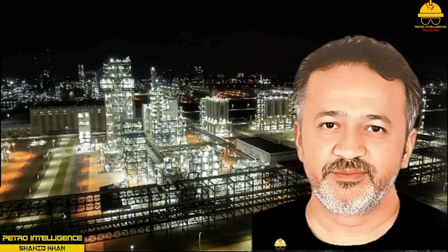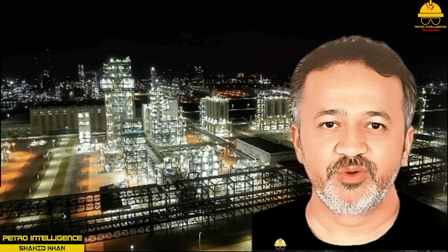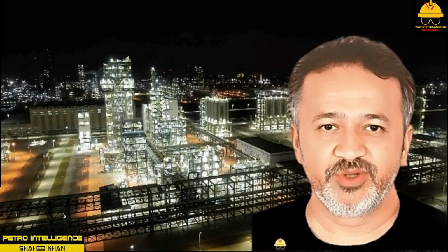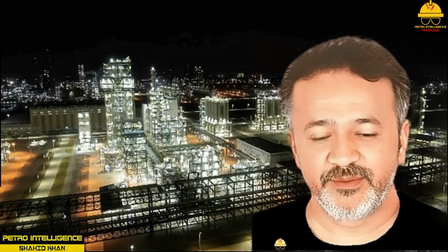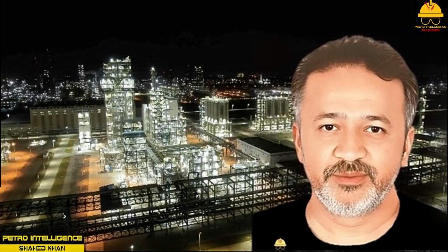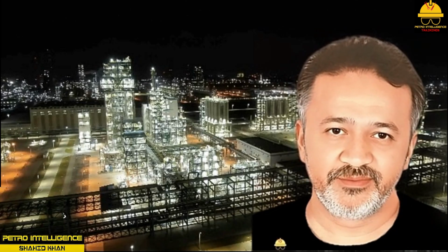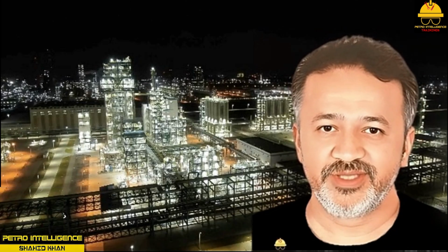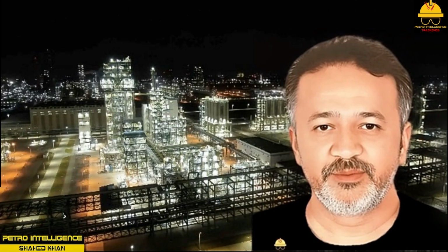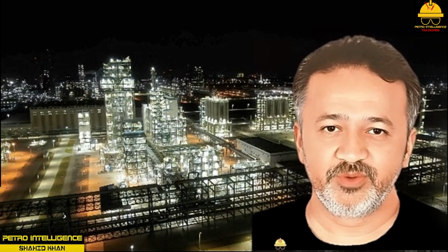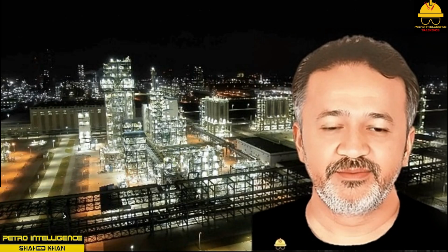Temperature symbols. Temperature symbols are typically represented as TI for temperature indicator or TE for temperature element. A temperature indicator is typically a gauge or a thermometer. A temperature gauge has a bimetallic strip inside that differentially expands with increasing temperature, creating a deflection that is correlated with temperature. These instruments are located in the field next to the equipment. Temperature elements are typically thermoelectric temperature measuring devices: thermocouples, thermal bulbs, resistance bulbs, or resistive temperature detectors, RTDs.